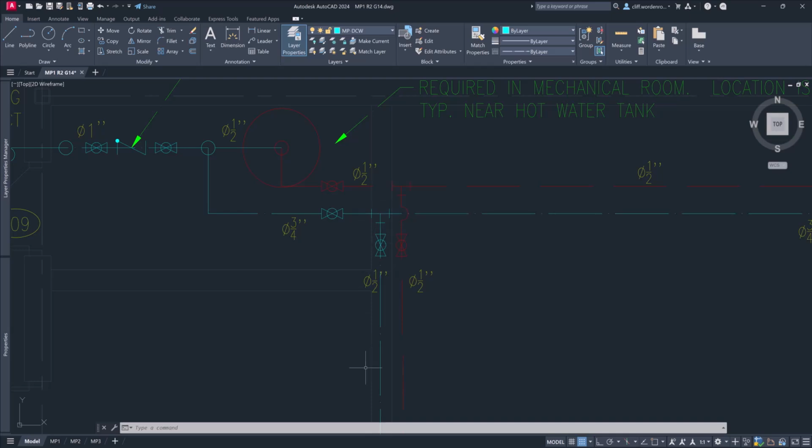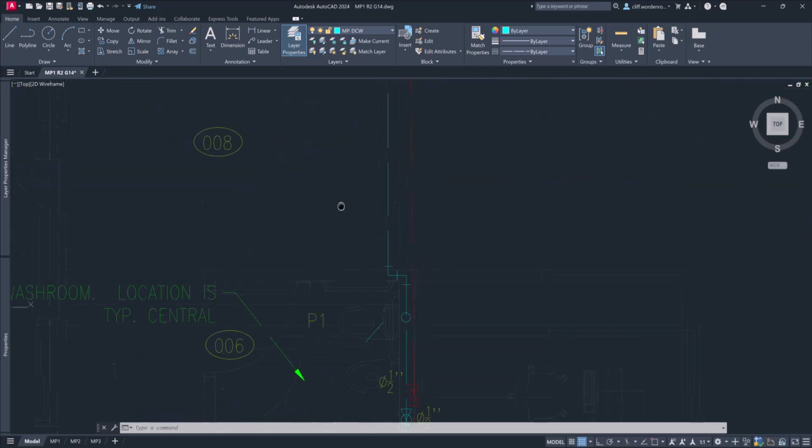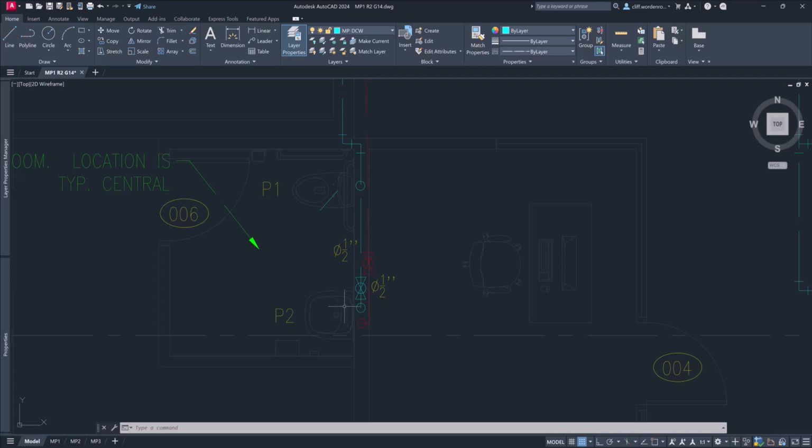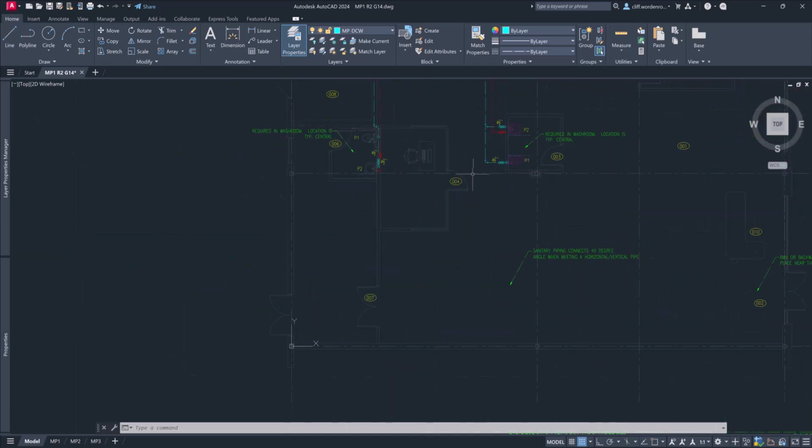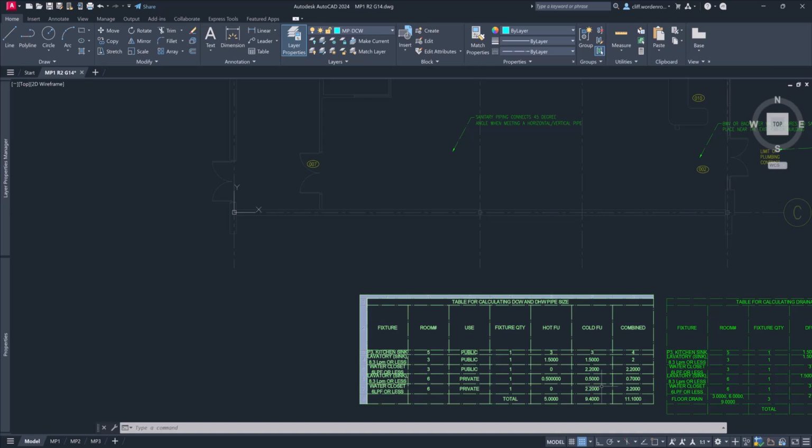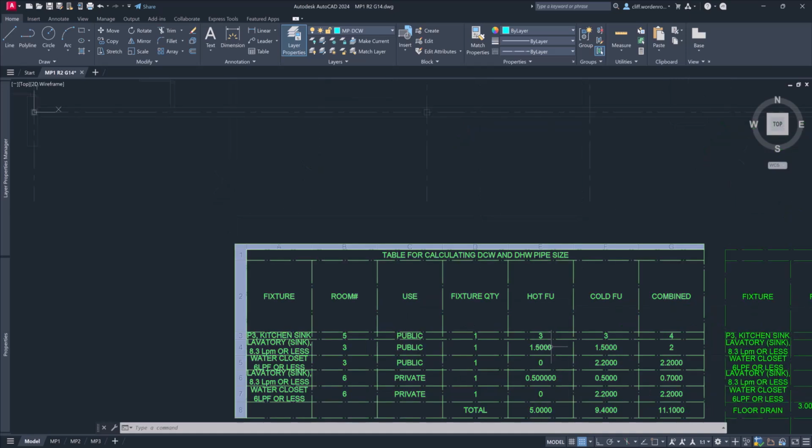All we need to do is size this last junction. So without fixture units, you guys can probably see that we have a sink in a water closet. The sink is a 1/2 inch. The water closet is a 1/2 inch. The total is the same as this one. Right, so we had, I guess it's a little bit less because it's a private lav sink.